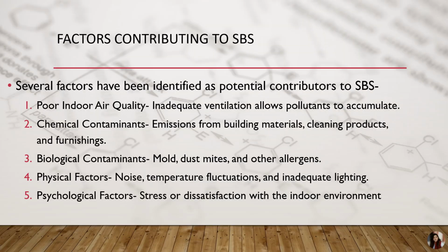The factors were, first of all, poor indoor air quality, because when you start to make a building airtight or close the windows and everything, at that particular time there is inadequate ventilation, allowing pollutants to accumulate. Based on it, there are certain cleaning products, furnishings, paints, and building emissions that themselves have chemical contaminants, followed by molds and fungus due to the wet moisture of the wall, dust mites, and other allergens that can also result in biological contaminants, which I can specify as bioaerosols.